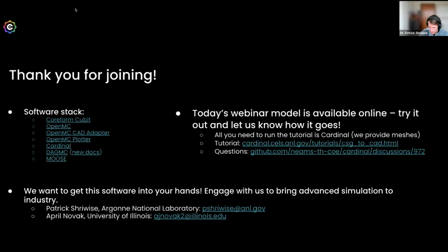Yeah, that's a good point, and that is correct. So for the workflow that we demonstrated today, where we're using that tally to generate subsequent geometries for the neutronics, is supported only for tetrahedral mesh. That's right. There's no reason we can't extend that to other linear mesh elements pretty straightforwardly. Getting into curvilinear is a little bit trickier. But that is the current extent of the feature.